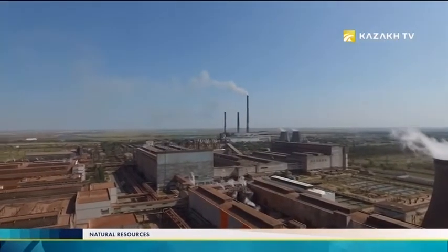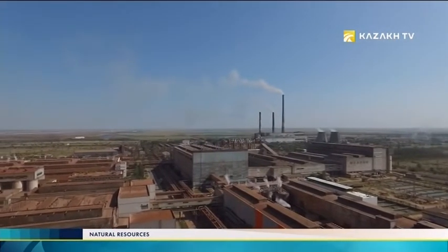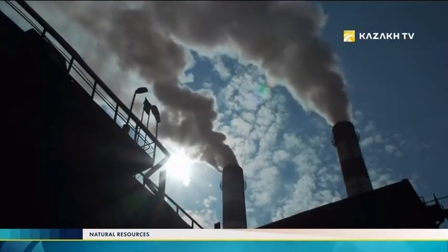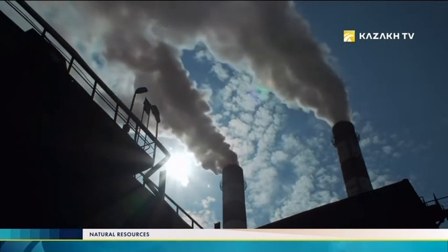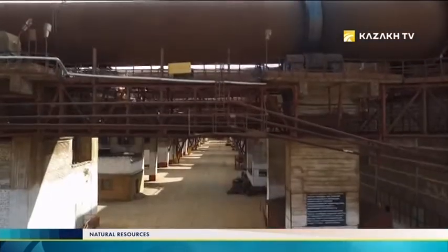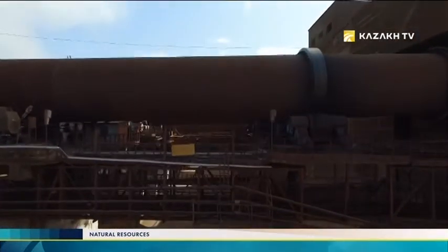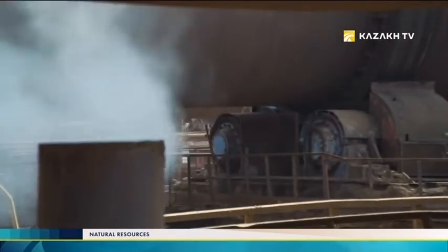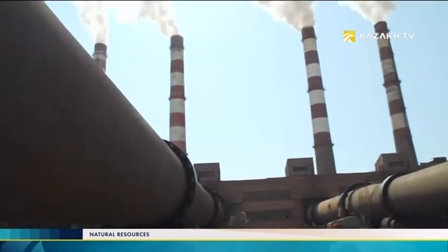The Pavlodar aluminum plant applies a unique method of processing bauxites with low content of useful components. The thing is that globally such plants use Bayer technique to produce alumina. But this method is more likely to fit for production of rich ores. The technique is about leaching previously crushed bauxites and further separating aluminum hydroxide from the solution. After absorbing hydroxide, the gravel can be easily separated. It is called red mud.